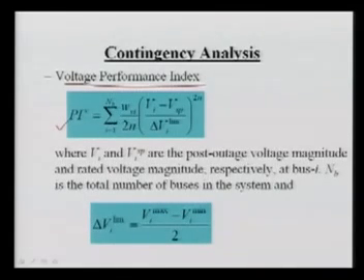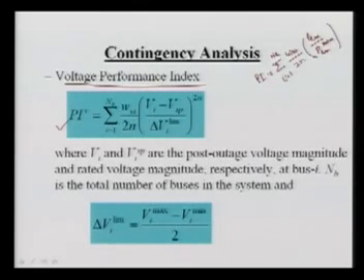Here again, this function is similar to the real power flow performance index. If you can see, I just defined here the PI for that, the real power flow PI, equal to the summation of i equal to 1 to the number of lines, of omega m over 2n, times P_Lm over P_Lm maximum value, to the power 2n. So this function is almost similar to this function.